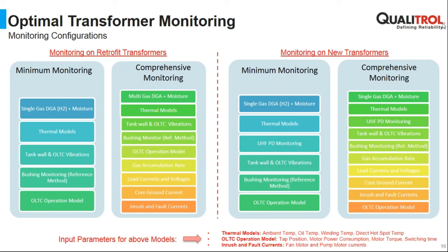From my experience, the power factor, or tan delta, depending on which part of the world, is a very powerful value, which covers most of the types of defects you may experience with bushings, and which helps you to detect early the developing faults.